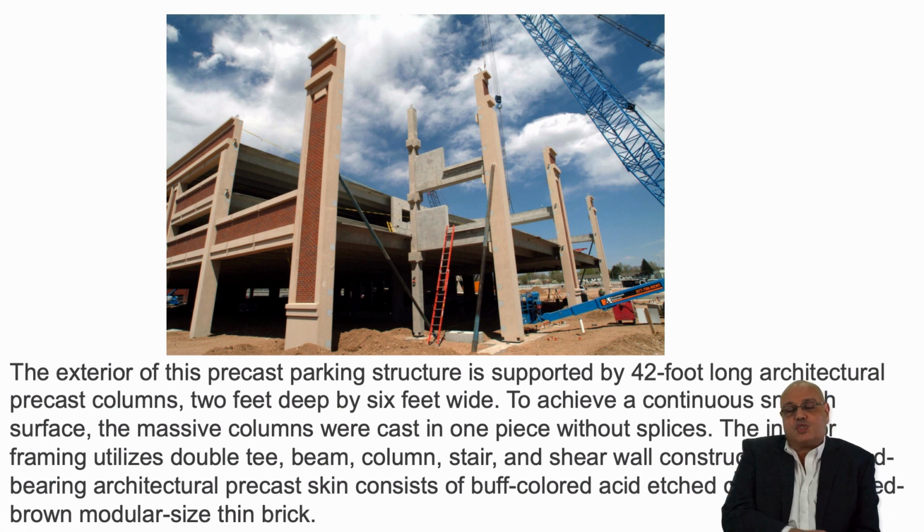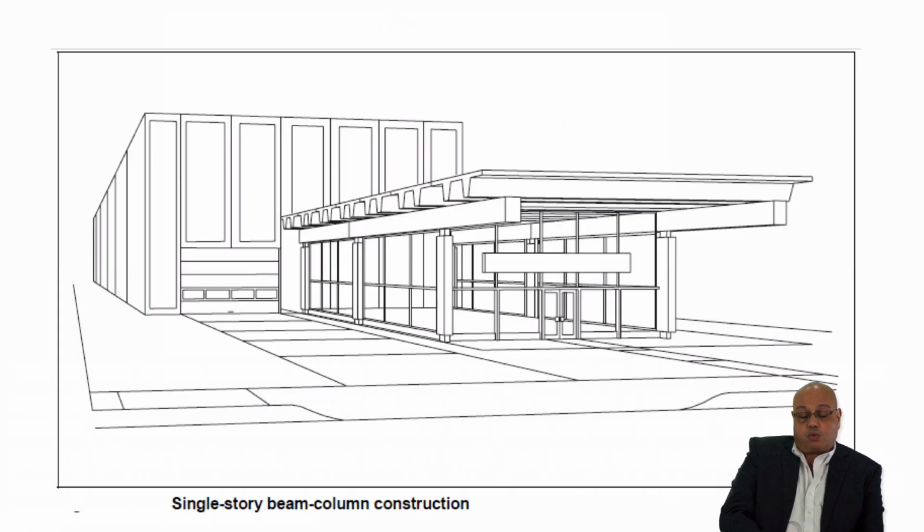And you probably noticed in the syllabus that I posted recently that you will be designing one of these double T's. So if you go to the parking garage at UNF or any other place, you will see the double T is primarily the major prestressed concrete component that you'll have, and it can be 60 foot long, it can be 50, it can even go 100, 125 feet as far as the length. Prestressed concrete is used for double T's, for any other beam, for columns, for the stairs, and for shear wall connections as well.